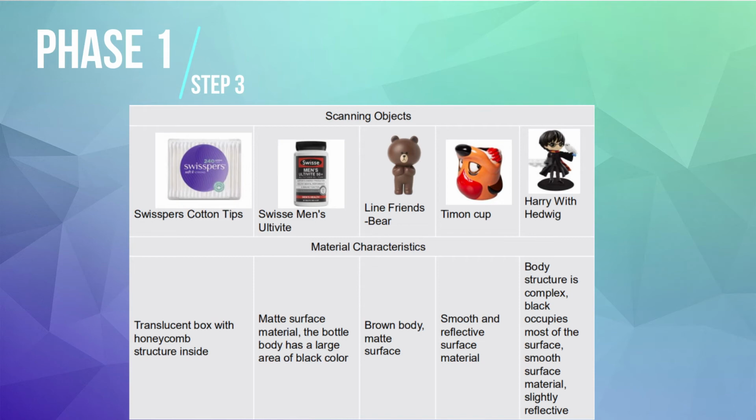Firstly, scanning black objects, whether smooth or matte, may cause the scanning results to lose some of the image data. Secondly, matte surface objects can also cause image data loss or noise increase. Thirdly, high reflectivity of the object surface will lead to scanner camera overexposure, resulting in color difference. Lastly, light scatter happens when it hits a transparent object, preventing the image from reaching the scanner's camera.